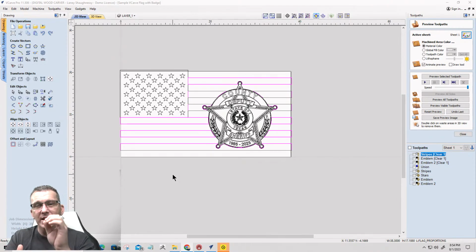And once we fine tune, hey, I can run my 1/8 inch bit in pine at 95 inches a minute, 18,000 RPMs, and I'm looking good, or whatever the case may be. Whatever those numbers are, I'm making notes all the time at the machine, and I'm adjusting my tool database accordingly. And when you get fine-tuned in, you're making beautiful chips.